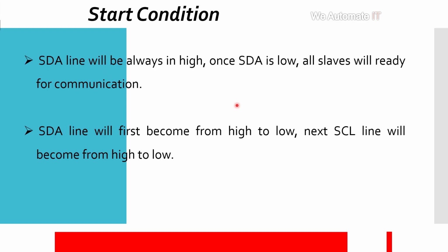Okay, so how does the address work? Two address formats are actually used here. The most common, 7-bit, supports 128 addresses. The 10-bit address is used when many devices are connected. So 7-bit and 10-bit I have already told you. 7-bit is most commonly used and supports 128 addresses. The 10-bit address is used when multiple devices are connected, and up to 1023 devices can be connected.